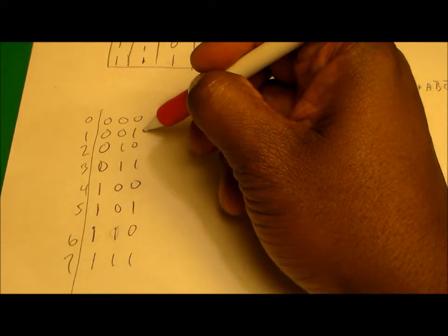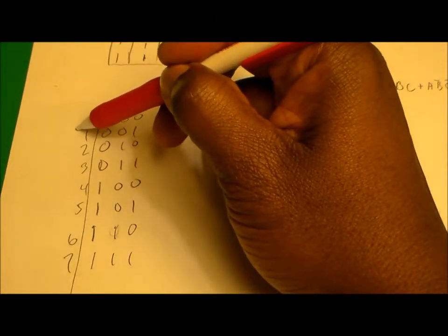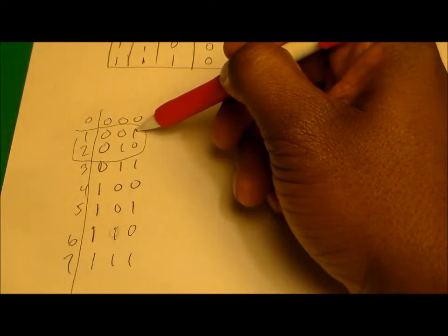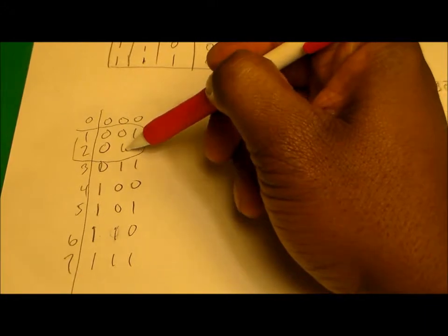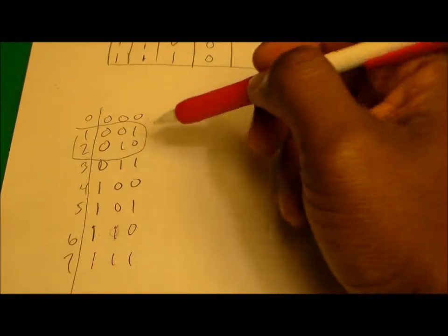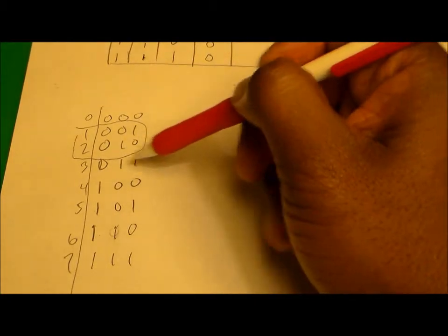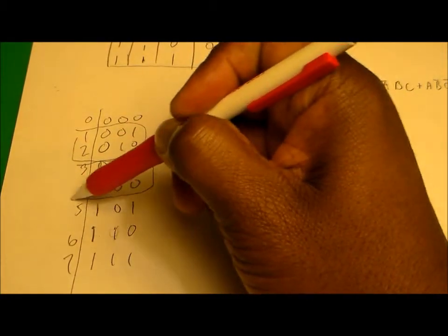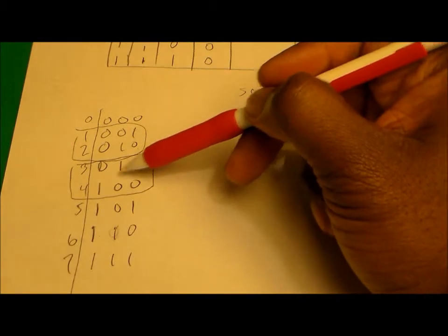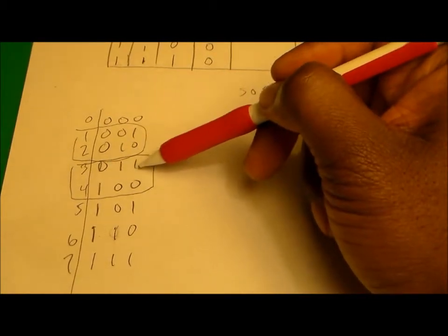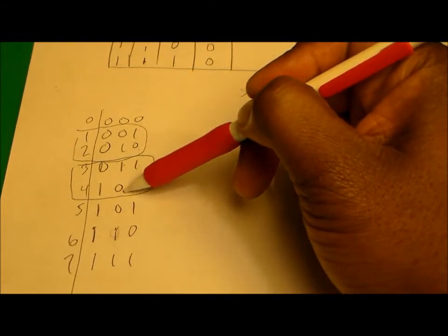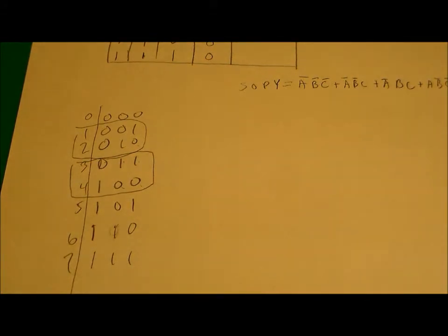And what you'll notice is, for instance, between here where we have our 1 and 2, there's a 2-bit change, because we go from having 1 in this position to a 0, and we go from having the 0 in this position to a 1. And then also what you'll notice is that when we go between, let's say, these two here, consecutive numbers, we end up with a 3-bit change. This goes from a 1 to a 0, 1 to a 0, and this one going from a 0 to a 1. Okay, so we don't want to end up using that if we're producing what's called gray code, which only allows for 1-bit change in between consecutive numbers.